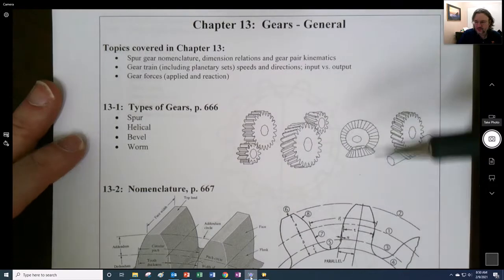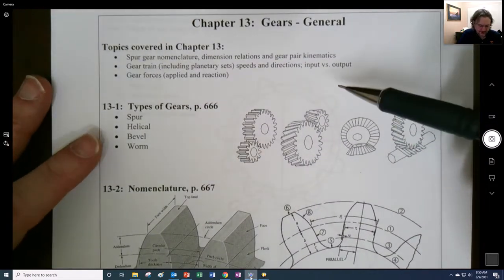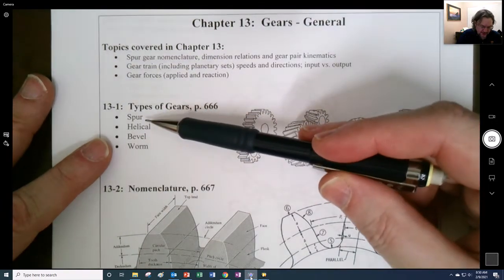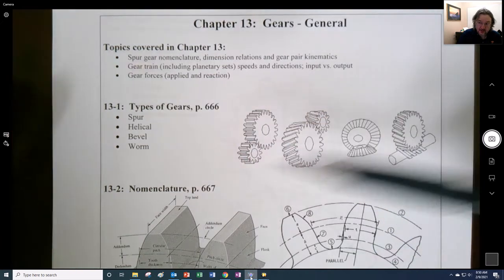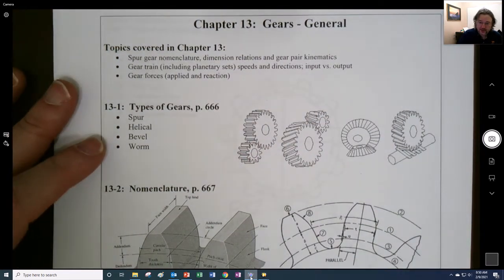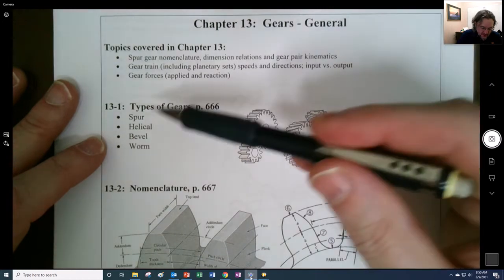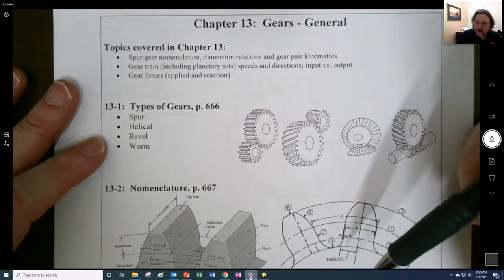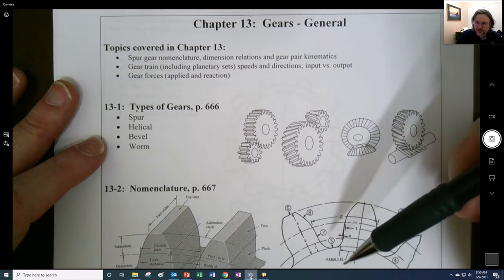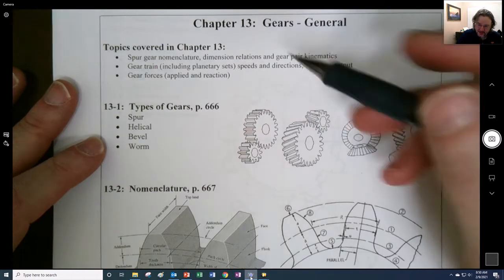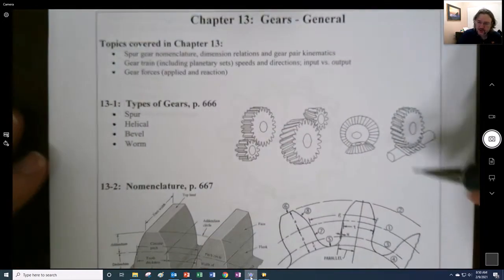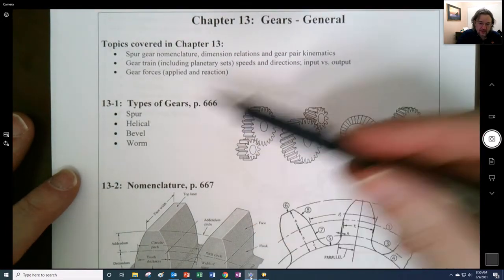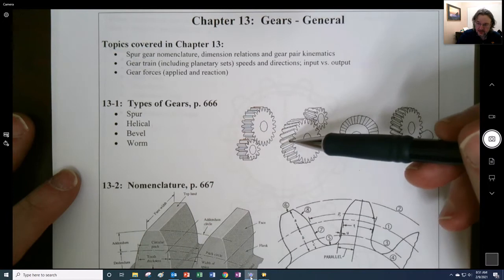It's good to have little categories of things. So let's break things down into different categories of basic gears. These aren't necessarily gear trains, they're just 2 individual gears that are connecting to each other. So I have some pictures here. We have spur gears, and you can think of the spur gears like spurs on cowboy boots, right? They're just basic gear lobes that are connected to each other, just straight out. You could contrast that with helical gears, which have a slant to the gear, right?